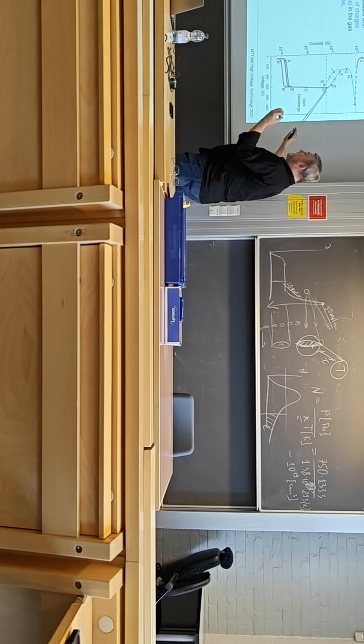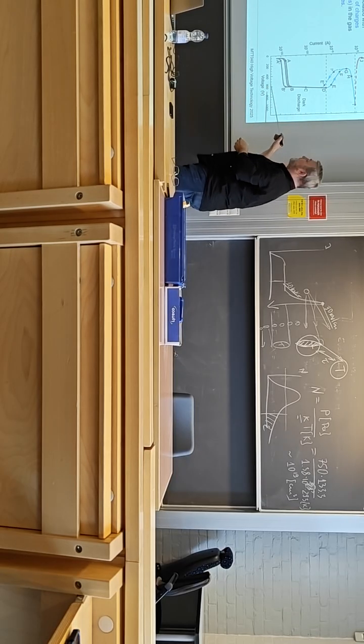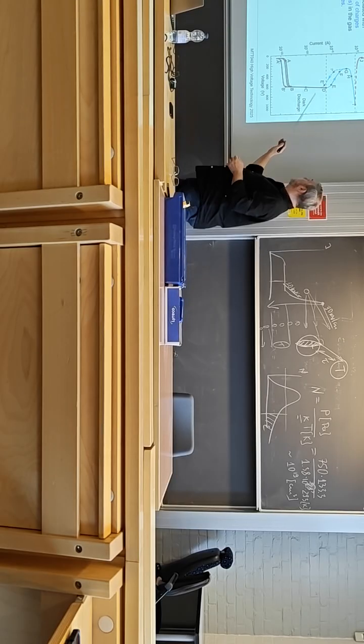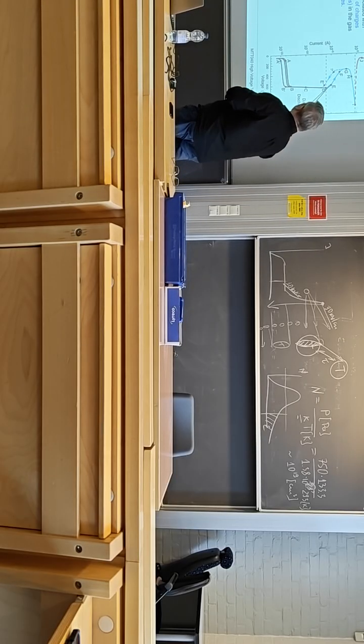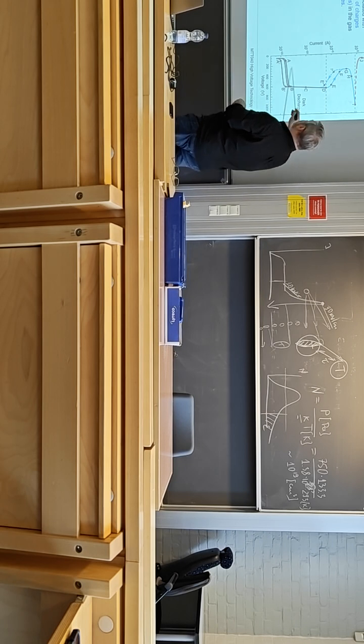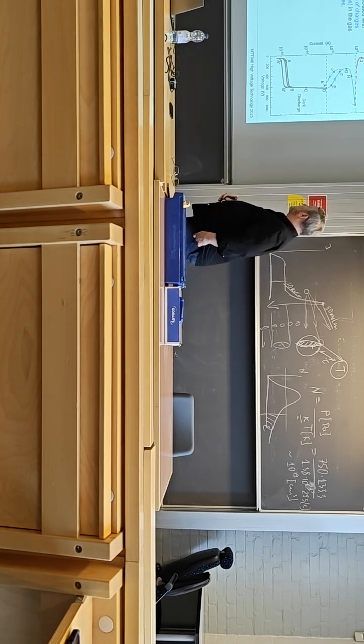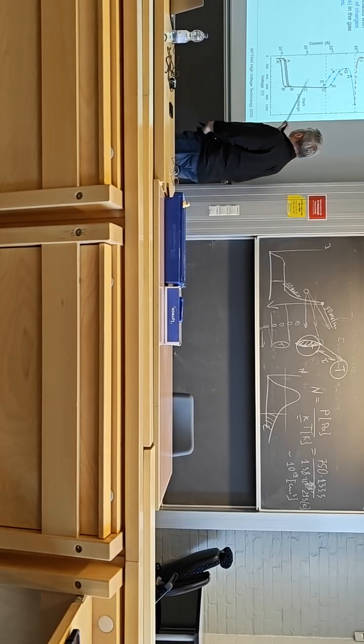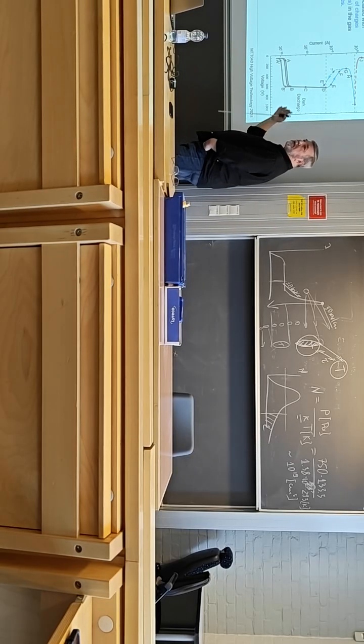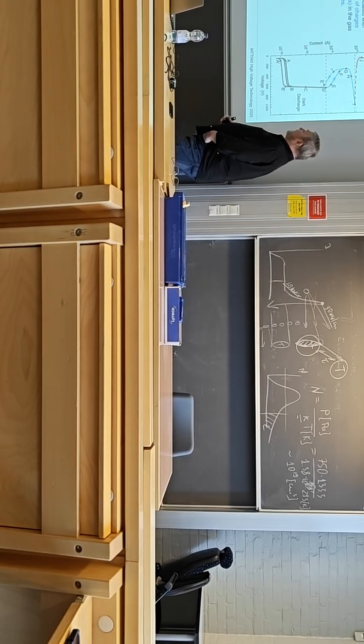So then this happens. This plasma region doesn't need such high energy from the external power supply anymore, because it can support itself. Then the current goes up, the voltage drops. Still some voltage is needed to support the processes, but a large portion of that just goes automatically, it's self-supported.